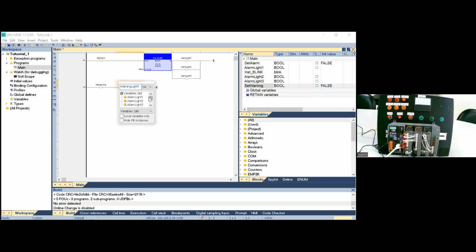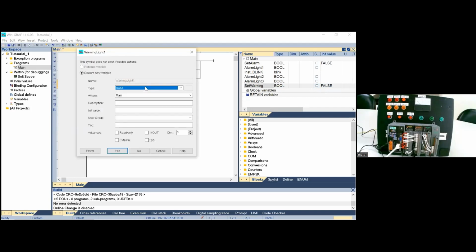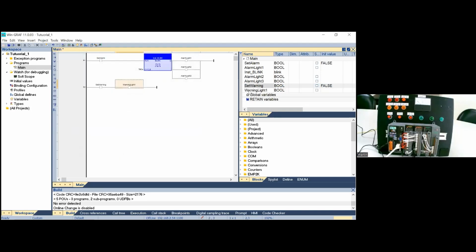1. Okay. A coil does not need to be initialized. We just leave the default setting. Again, the new variable name is being shown in the variable editor and also on top of the coil element. Now we want again this light to flash every, for example, 3 seconds.